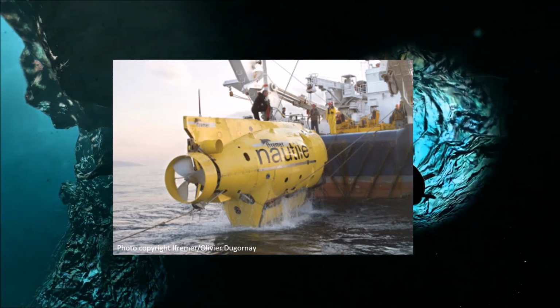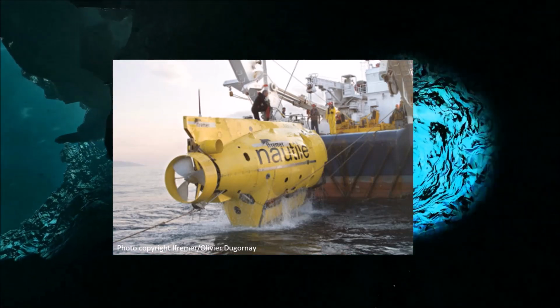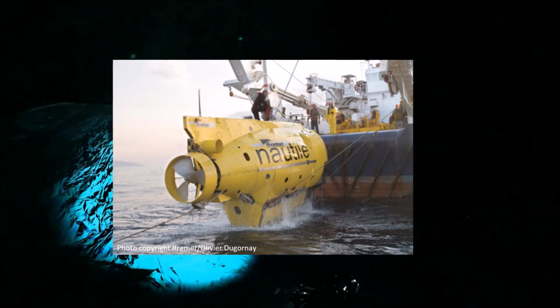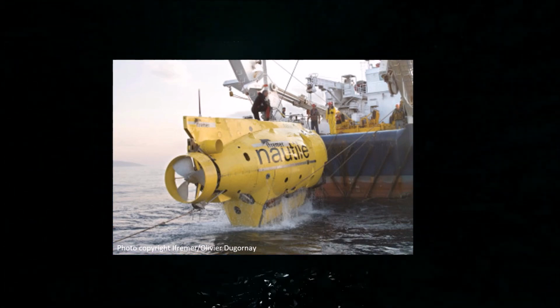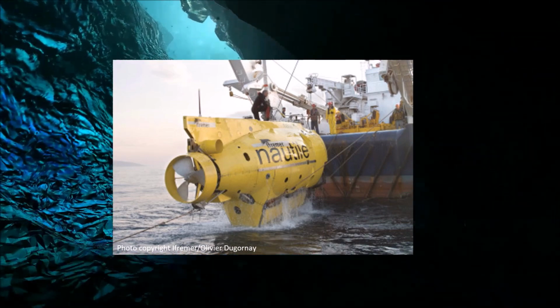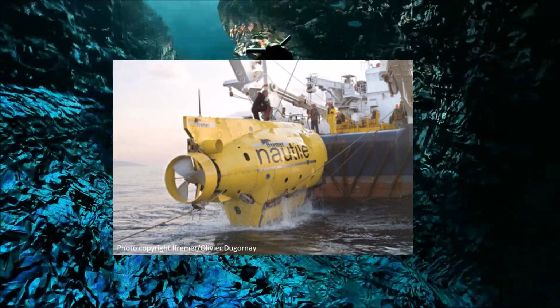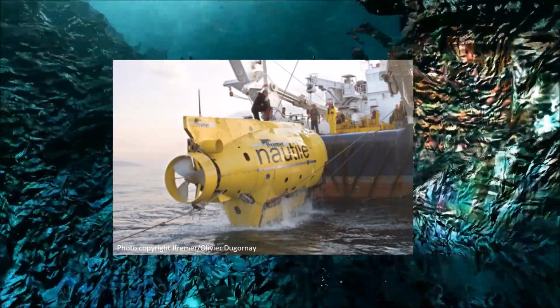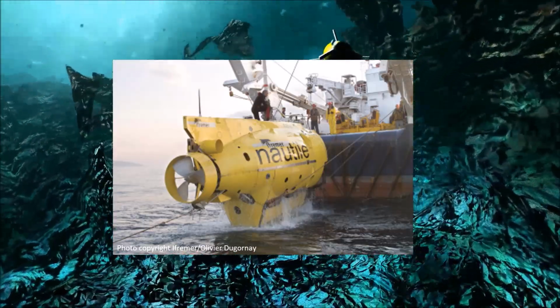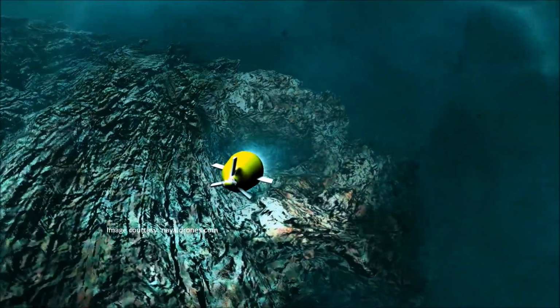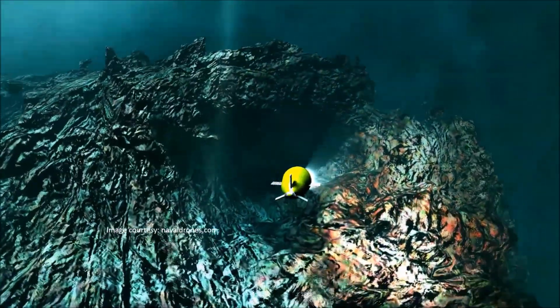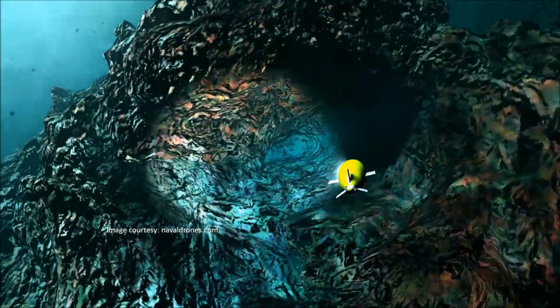They make use of composites but not for the pressure chamber, which is metallic for all manned vessels. All the yellow fairings are glass reinforced composite, but the main pressure vessel housing for the crew of 3 is a titanium alloy sphere. For some unmanned submersibles, composites are used for pressure resistant hulls, especially for those which are autonomous.